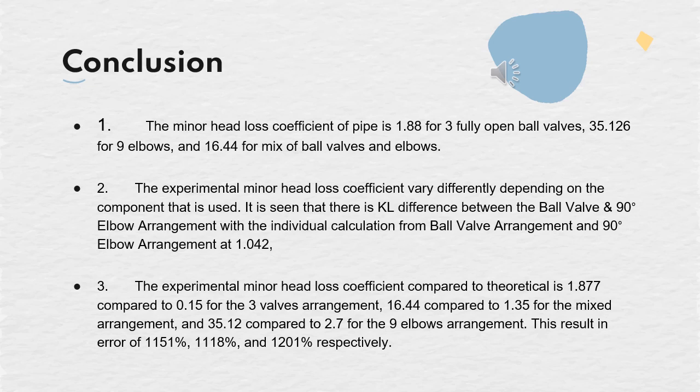Third, the experimental minor head loss coefficient compared to theoretical is 1.877 compared to 1.15 for the 3 valves, 16.44 to 1.35 for the mixed arrangement, and 35.12 compared to 2.7 for the elbow arrangement, which means the resulting errors are 1151%, 1118%, and 1201% respectively.